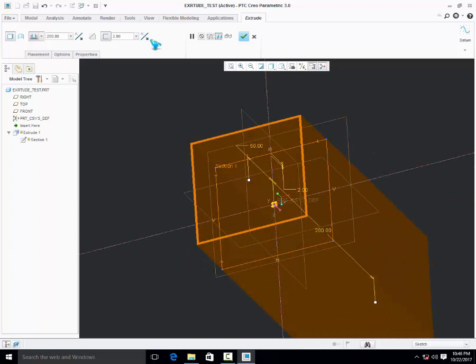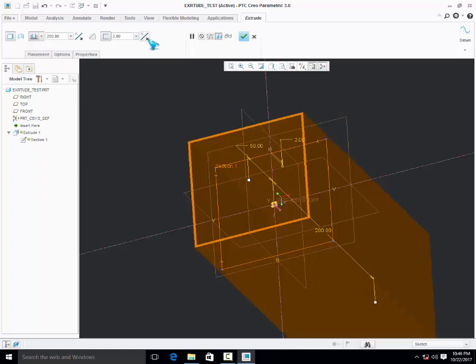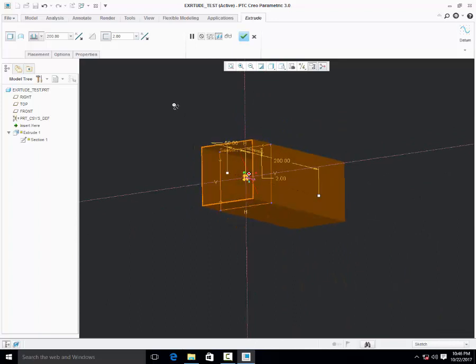Here again we have the option to flip in which side the thickness is required, either inside or outside. See, it's showing outside and again inside. This is all about extrude as a solid. This symbol is extrude as solid, this symbol is thicken.